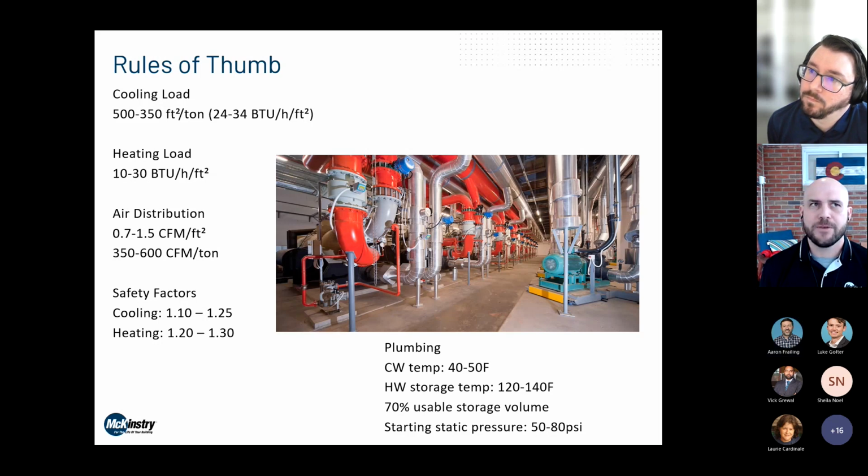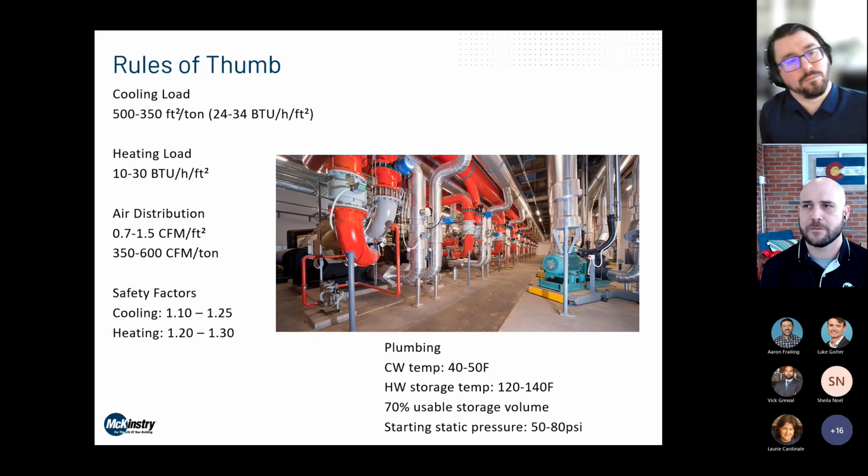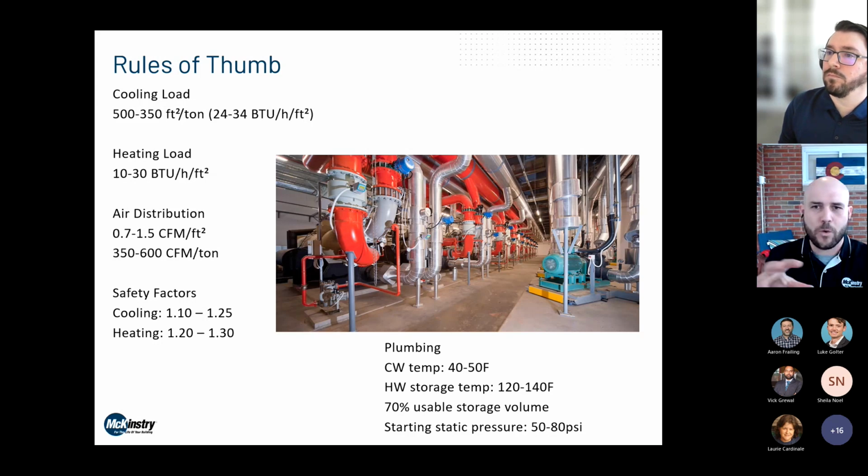Yeah, I think VRF as a technology can potentially offer some flexibility. If you had, perhaps, 10 tons of cooling and 20 half-ton indoor units, you could have some flexibility as to where all of those actually get installed within the space.